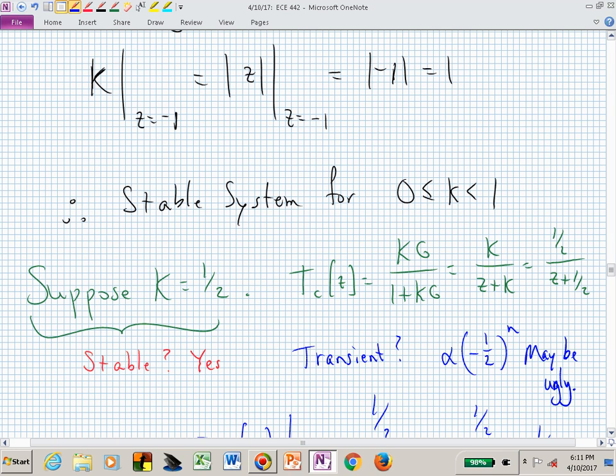It's going back and forth, but you don't have an overshoot, do you? It's just an exponential decay. You don't have a peak either. It's not overshooting, so you don't have a peak time. If you have a real pole that's dominating your response, it's the only pole there, you just have a settling time that you can calculate. Your percent overshoot would be 0, and your peak time would be 0.